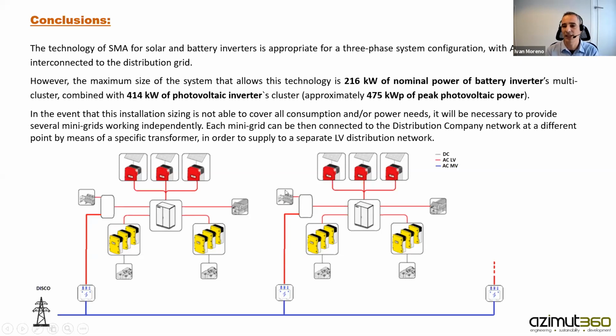The system detects the presence of the grid, and if we have utility grid, we use it in preference to the generator. But if the grid goes down, it is quickly detected and it switches to the generator. So the auxiliary support is always present.